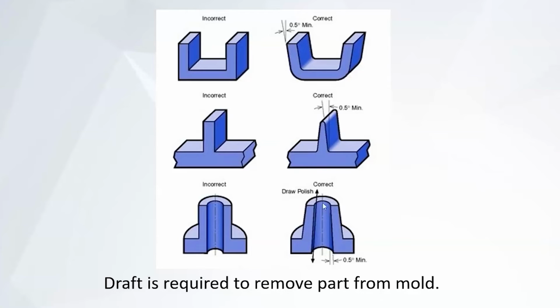The same is true here with this through hole, where the mold is going into this through hole to block plastic from going in there. Once again, if it's a straight edge, it will make removing the part more challenging. You just add a very small draft angle. They're saying a 1/2 degree minimum. That's pretty small. Typically, I see more like 2 to 3 degrees. So draft is something that you have to take into mind.